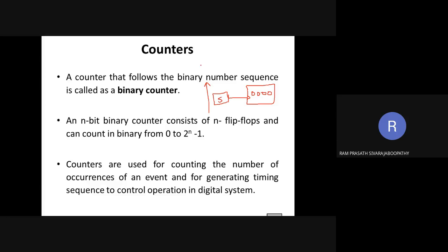Initially the waveform is 0. At the moment when the person is near the sensor, it will go from 0 to 1. It will maintain that till the person crosses. Once he crosses, it will go low again. If the next person comes, it will again behave like this. So what it means is, for every one person that enters, it generates one low to high transition. That means a positive edge.